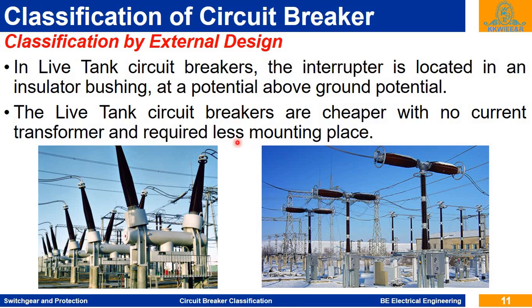For live tank, less mounting space is required, no CTs. Because of this, it is cheaper. So based on this external design, these are the types of circuit breaker: dead tank circuit breaker and live tank circuit breaker.